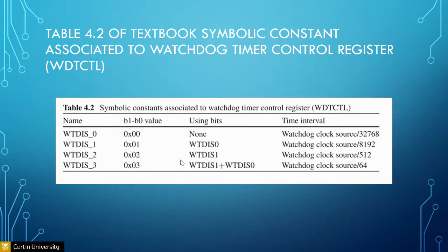It is useful for bit masking. Again, I want to repeat, these are symbolic constants that are in the library. Bit 0 means 0000 0001. This is bit 0. Okay, bit 1 means something else. Now these are constants associated with this name, because it's very common to use this watchdog source. Okay, so you want to have the watchdog. If you want to take it from the auxiliary clock or the master clock, you divide it by such a value to make the count slower or faster.